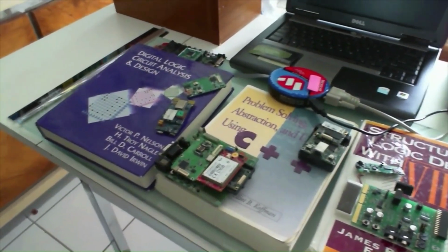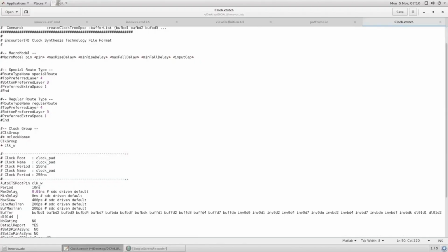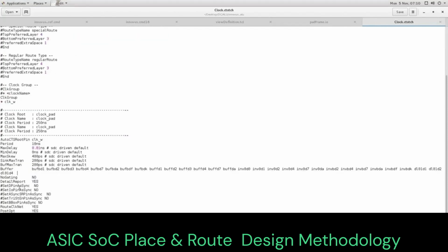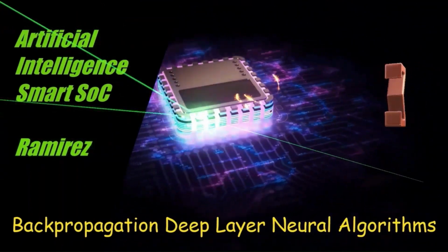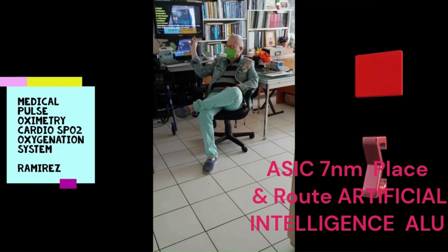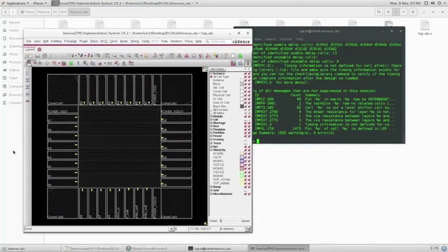Many interdependencies exist among placement, clock and scan optimization, wiring, as well as hierarchical design planning. The general design flow is as follows. First, identify connections to be optimized after placement so that they will not influence placement at all. These include the scan and clock interconnection latches.